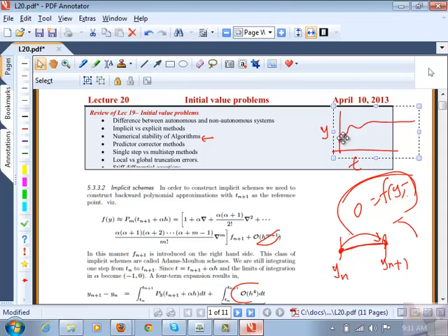So the reason why a dynamical method like this works, even if you use a very large step size, and this is a trick that is often used: I'm interested only in the steady state, and I want to use a dynamical integration scheme, but I will use a very large step size, and an implicit scheme so that stability of the numerical method is preserved. Since I'm not interested in the entire trajectory, I can take a large step size and sustain a lot of errors on the way to the steady state. But once I reach the steady state, it's called the pseudo-transient method to get the steady state. So you might come across this terminology, a pseudo-transient method.